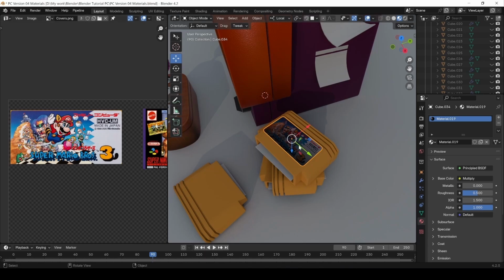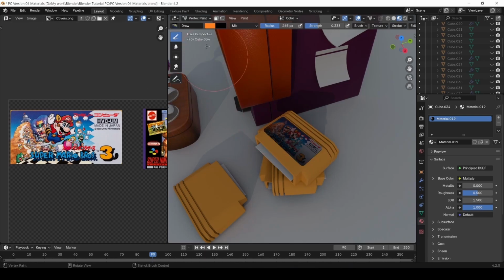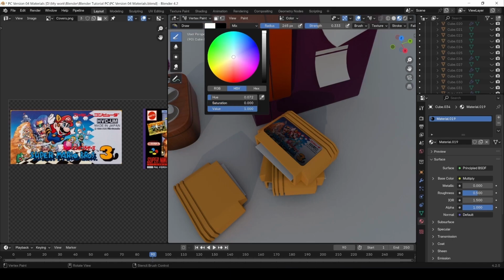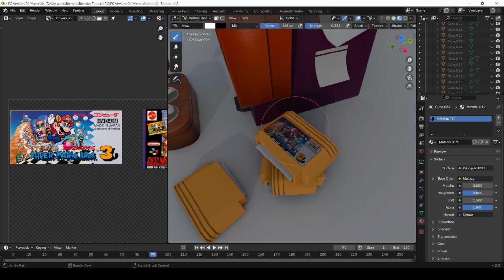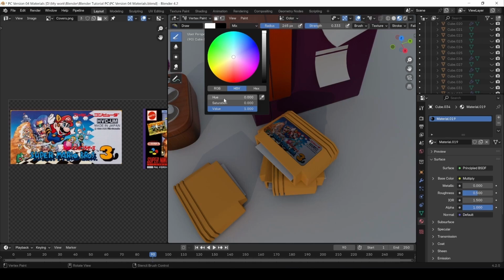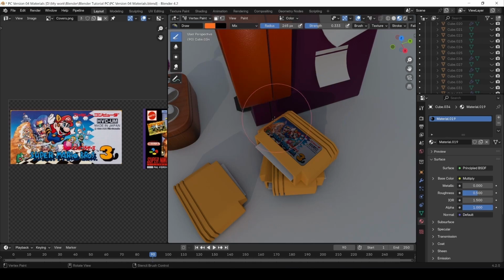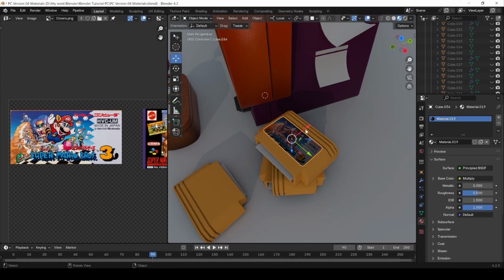I'm going to change the color too. We can go to object mode, vertex paint again, and choose white. Okay, and make it all white, and then go control and make this side a little bit black, just a little bit. Then some reddish color like we did before, put it right here, something like that, and control to have darker colors from here. And then let's do the same thing, go to object mode.